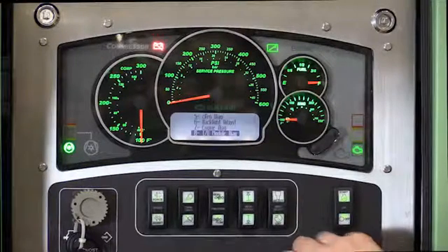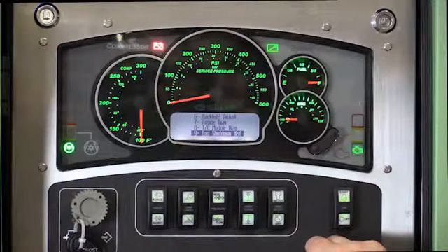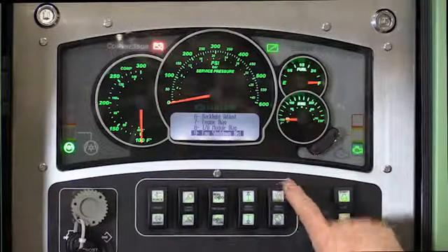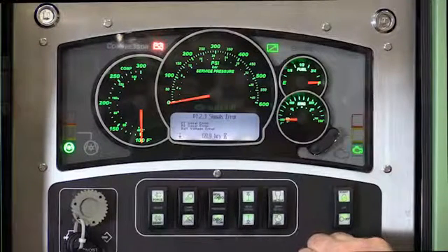The last and 9th menu item available in the Settings and Configuration menu is Engine Shutdown History. The C-Pro is capable of storing up to 5 shutdowns. Upon entering shutdown history, the latest shutdown will be the one displayed, and the hours of when it occurred. This down arrow indicates there are more shutdowns stored to view.